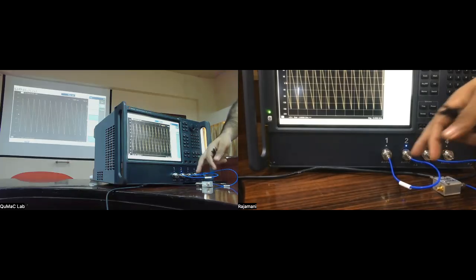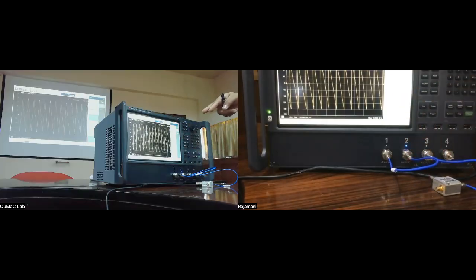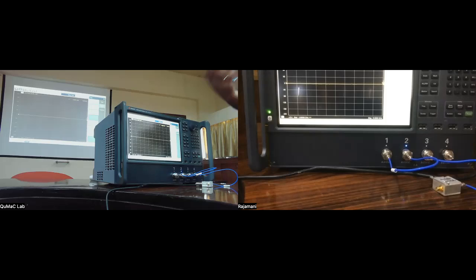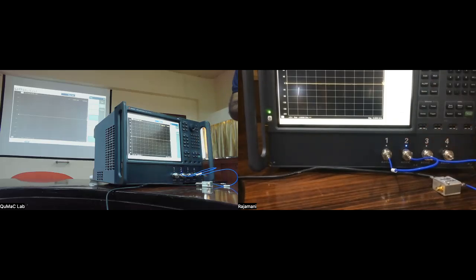So that's why usually I connect the cables to the two ends and dial in a delay time, which is basically telling me how much time it takes. So this number, 1.56, tells you the travel time from this end to this end.